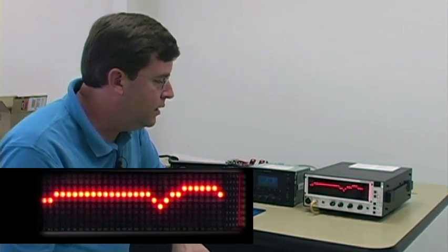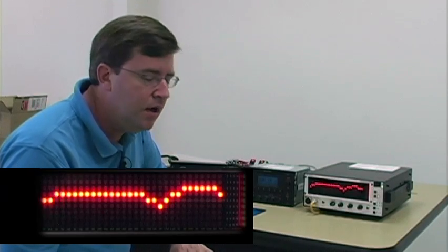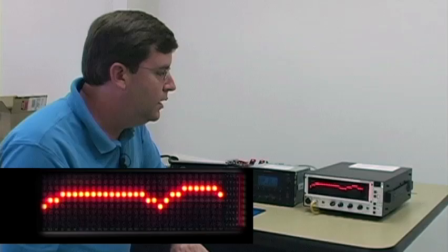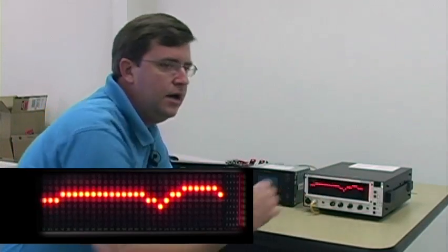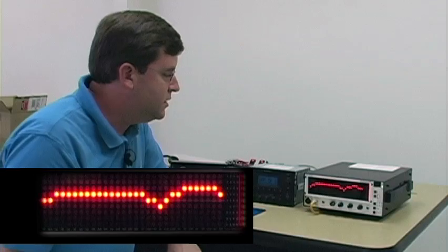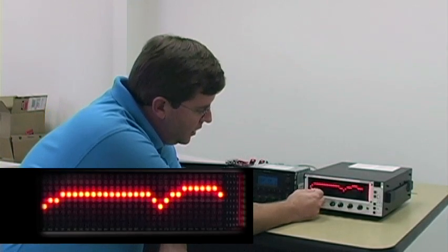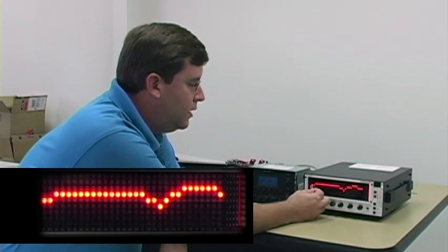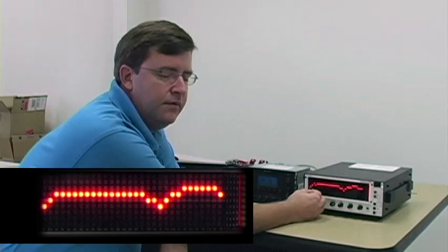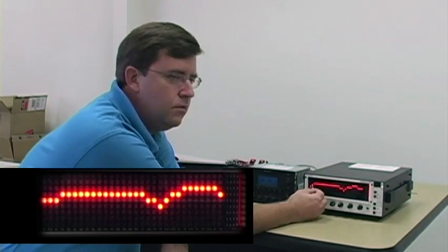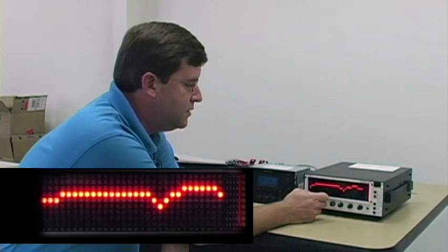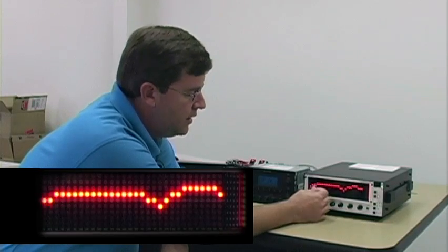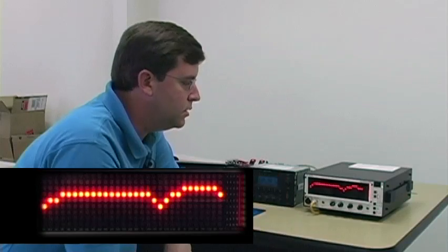What we see here is a pretty typical OEM frequency response curve. Instead of that nice flat line, which is our target, what we see is that there is a significant decrease in energy below about 40 hertz. They do this typically to protect factory speaker systems from damage when the user gets a little too aggressive with the volume control. So by rolling that energy off, they actually limit excursion.